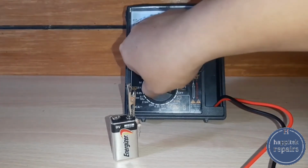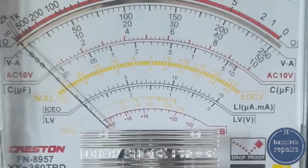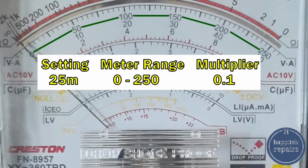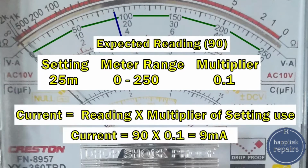Let us set the ammeter to 25 milli. We look at the meter range of 250 with a multiplier of 0.1. The expected reading we should get is around 90, since the product of 90 times 0.1 is 9 milliampere.